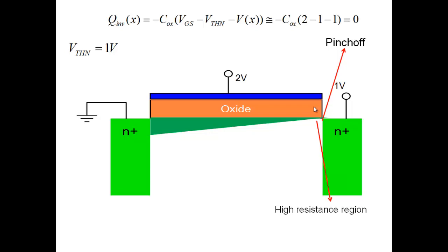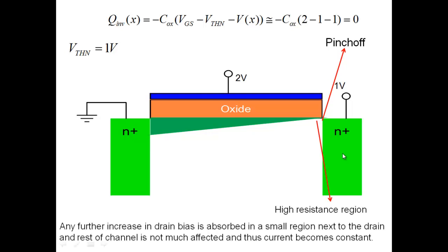If I take, let's say, the whole channel length from here to here as 1 micron, and I divide it into 0.1 micron elements, and I look at the resistance of that 0.1 micron element here versus one here versus one here, you will find that the resistance of this particular region would be very high because the carrier density is very, very low. Right? Okay.